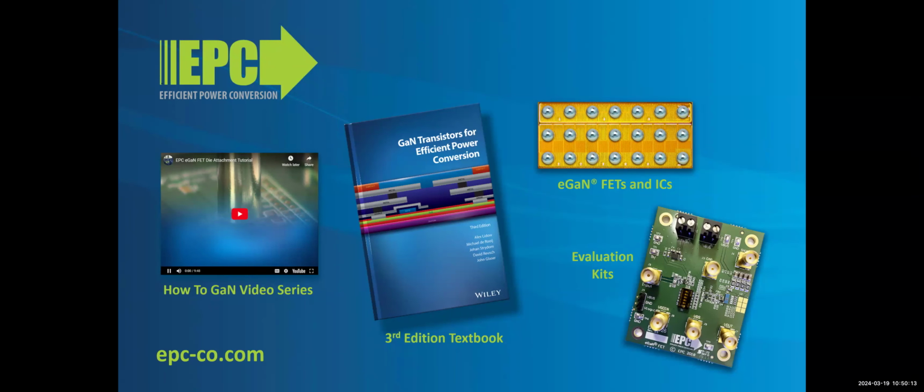On a practical level, I'm seeing customers trying to use less than 1 meter or 2 meter cable with the gallium nitride inverters, but there's always a trade-off with EMI. It's not really a matter of reflection in this case, it's really a matter of the EMI generated by the cables.